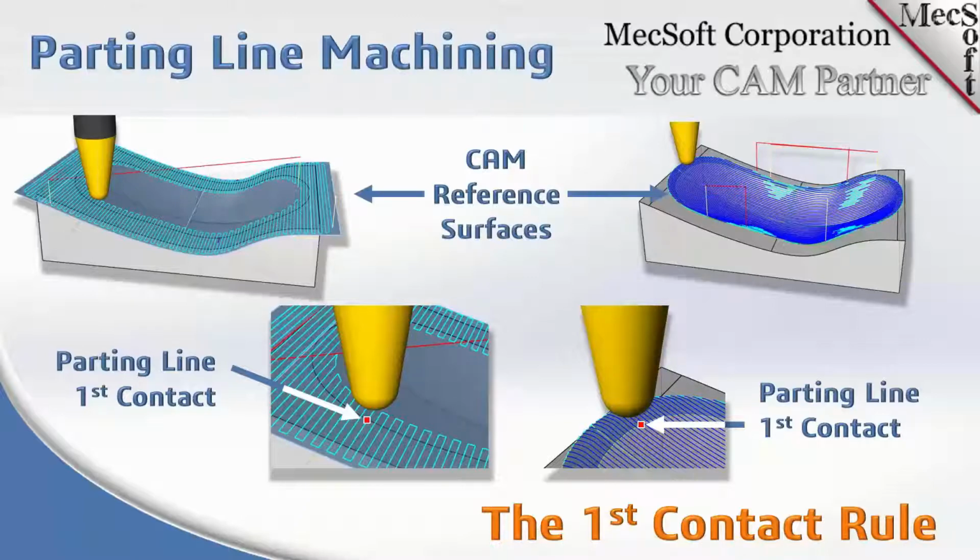So that tool will just say, howdy parting line, I'm going on my way. It's touched it and it's continuing to cut in other areas. It doesn't stop on the parting line. Like I mentioned, it doesn't roll over the parting line, and it doesn't roll along the parting line. And that's what these protection surfaces are used for. I'm telling you how to do it, but we're going to show you the end result of using this technique and not using this technique. And it's a very stark comparison.